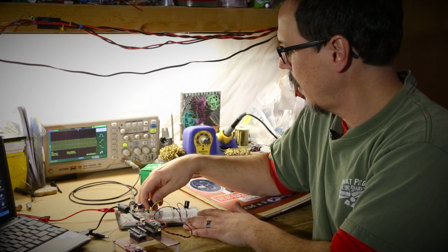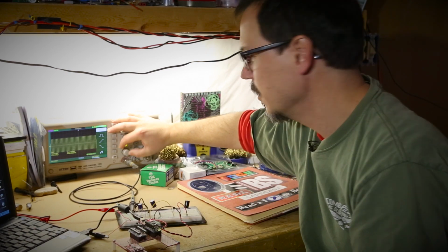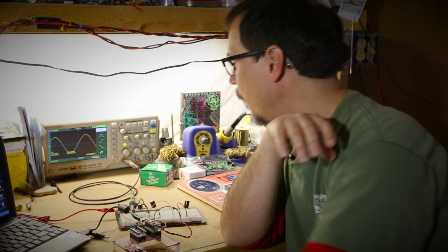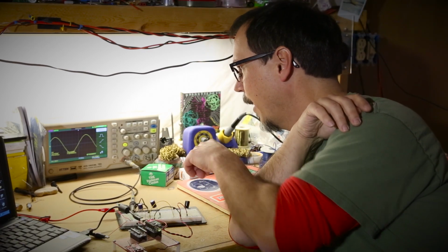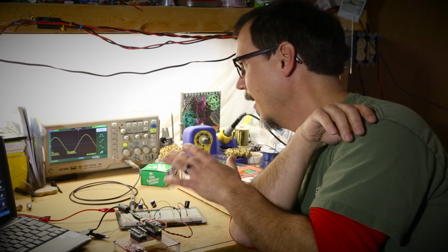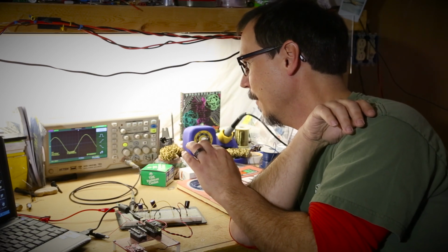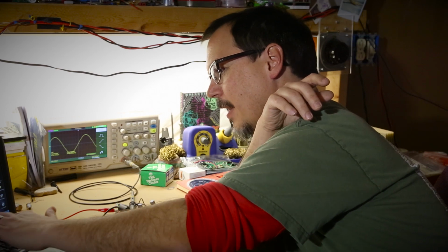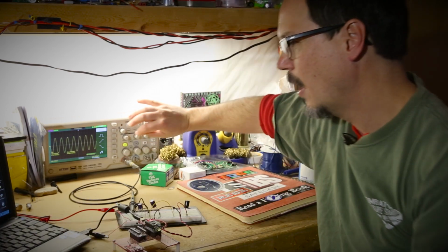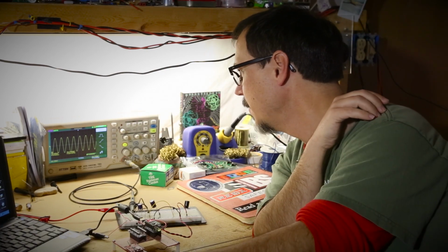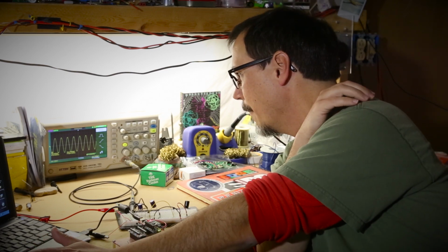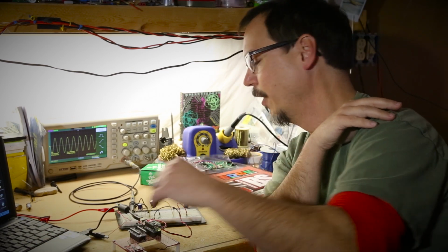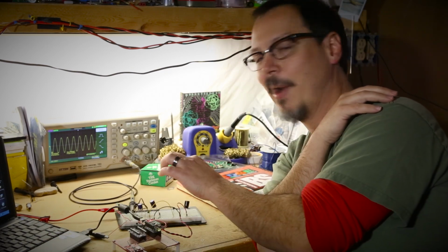And you yank that cap out, so let me adjust my voltage level. I'll bring it down to 20 kilohertz. And I got my output, right, gain of 10, and my output is about 976 millivolts peak to peak, okay? So the low frequency cutoff, I'll just take it down to 20 hertz. So now I'm at 20 hertz and I'm still at 856 millivolts. So I'm still above my low frequency cutoff without that bypass cap.